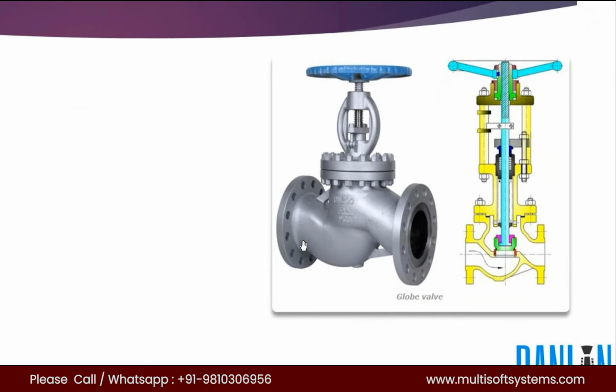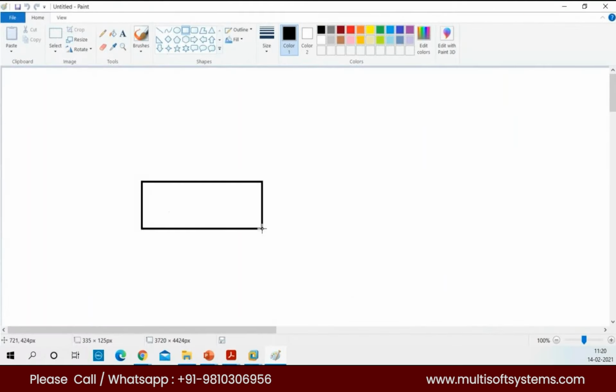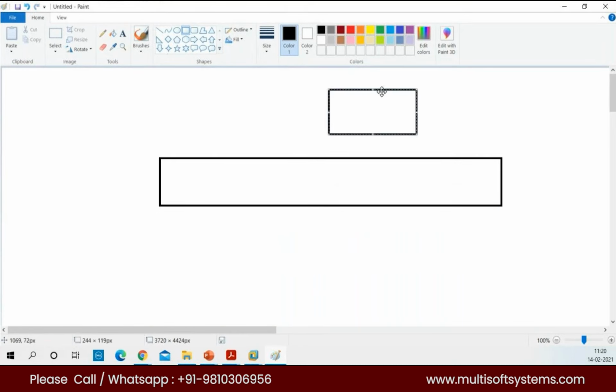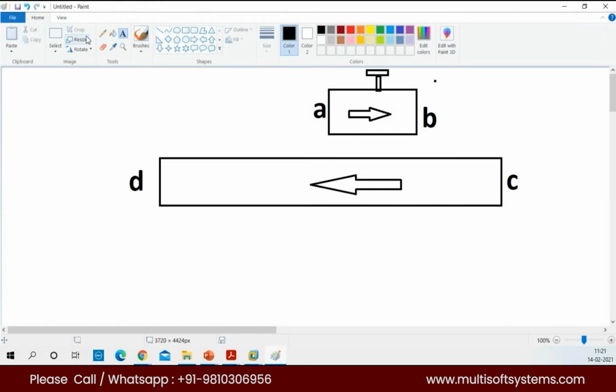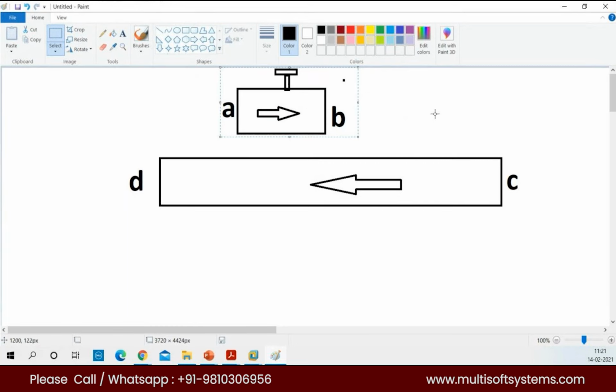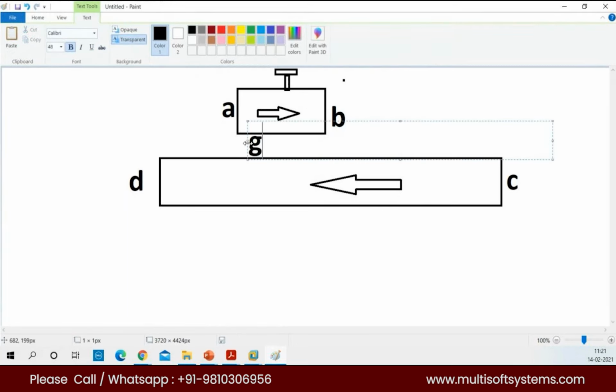Mr. Manoj, I have a small question. Here, this valve, maybe you can also explain how we are making the valve, because if we have a small pipe like this, and we have to introduce a globe valve, so A to B, and here the flow will be like this, how are we going to place the globe valve in the layout? Yeah, we have to place it along the flow direction. So the B to A will be the direction. Okay, that is the thing for the globe.